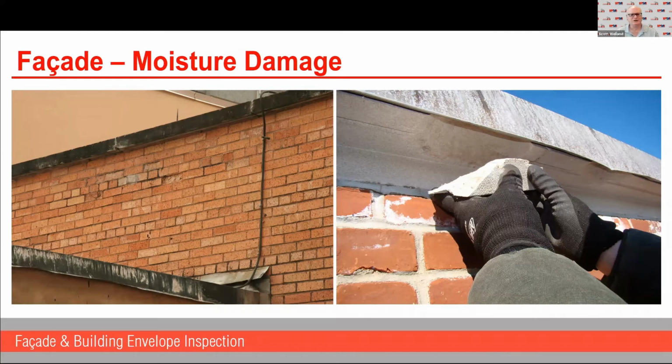Another mechanism is related to osmosis, and that's when salts that occur naturally in building materials are picked up by moisture and travel through the brick, and then you get what they call sub-efflorescence. And what happens is the water evaporates out the face of the brick, leaving the salt behind. And when that salt crystallizes, it expands in volume, and there too, it causes like 3,000 to 5,000 psi of pressure, and like I mentioned, there's no stopping it.